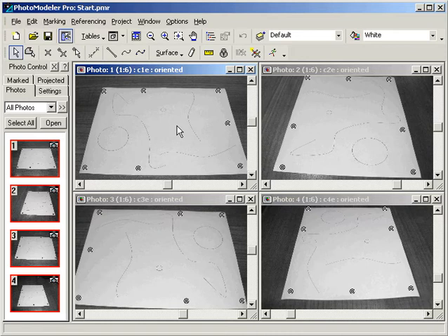We will explain using this curve here. You start marking a curve using your 2 best photographs. You look at the main axis of the curve, which in this case is horizontal. Then you look for another photograph that is rotated around this axis. In this project, photographs number 1 and 3 have the best rotation about the curve's horizontal axis. If we look at photographs number 2 and 4, we can see that the axis of the curve is vertical, and the position of the camera has changed vertically. These photos will not work well for this curve. We will demonstrate this again later.